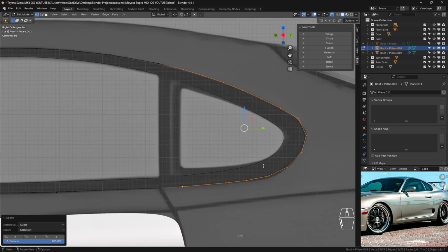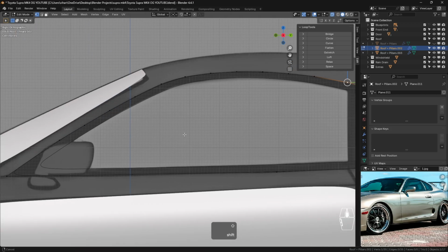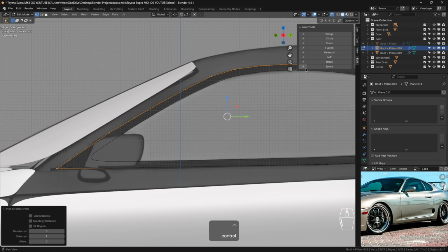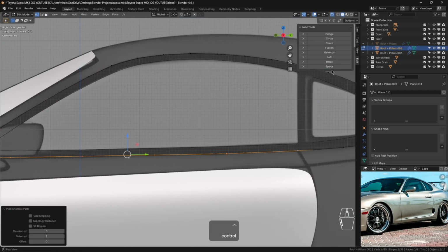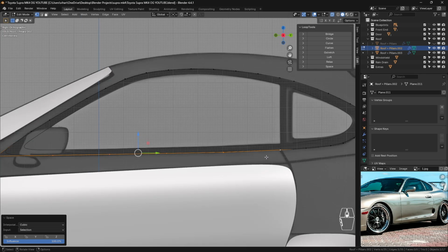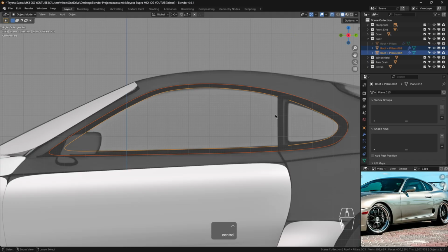Just do the same thing that we've been doing. Same thing. Select all the way from there to here. Just press Space. And then here again, all the way here, right? So we've just divided into a few chunks now. Now we're just gonna be selecting both of these and just press Ctrl J. That's gonna join both of them.